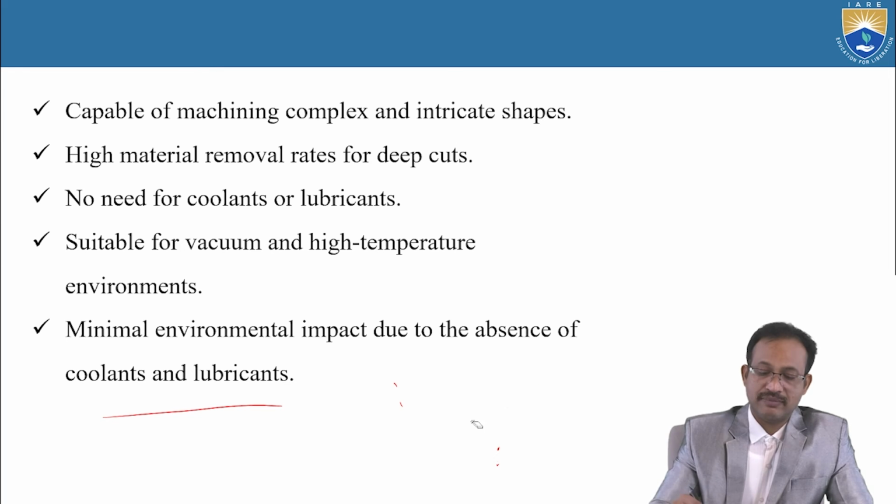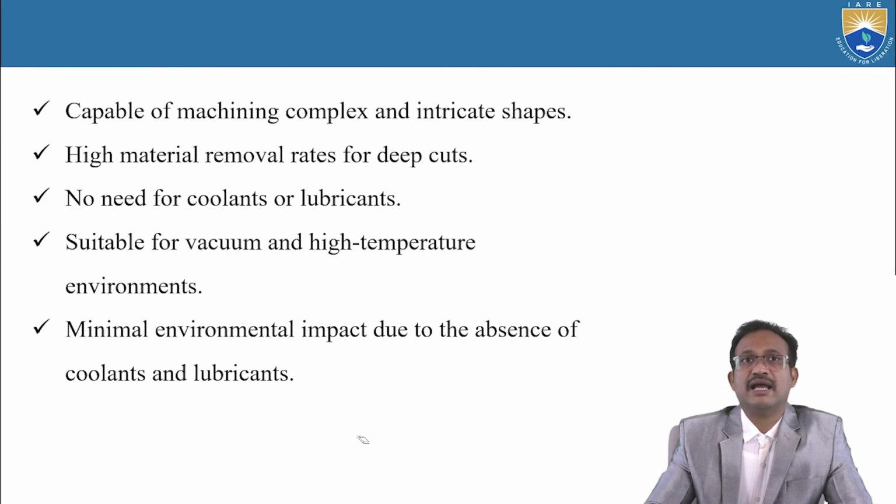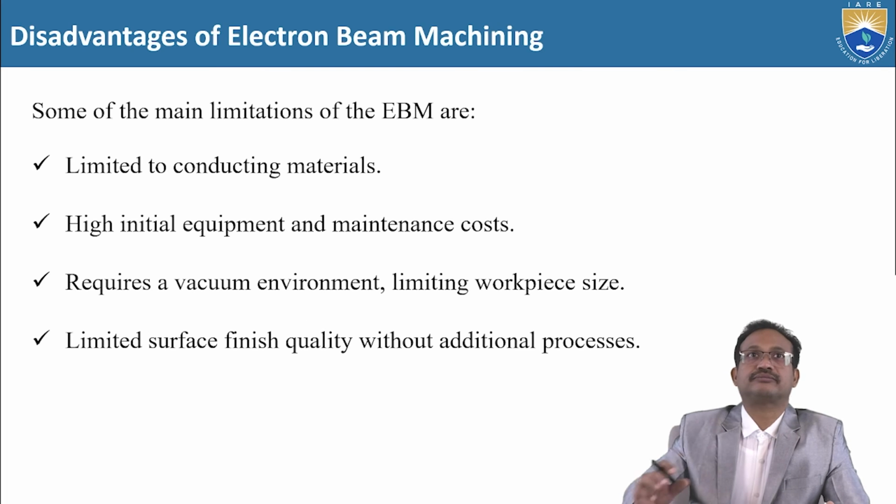Simply the beam of electron cuts the material, and there will not be a heat affected zone, and there will not be any requirement of coolants and lubricants, so that there will not be any chemical reactions between the coolants and lubricants with the workpiece material during the machining of the workpiece.